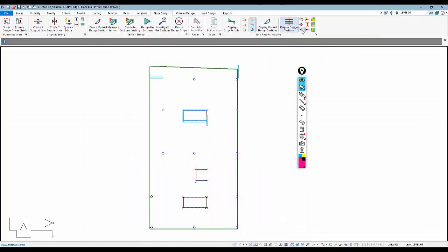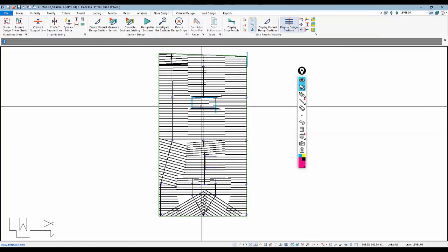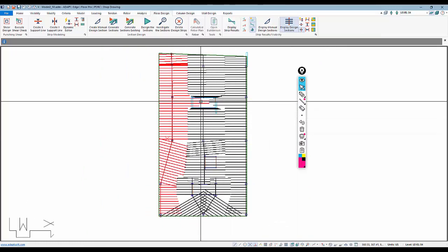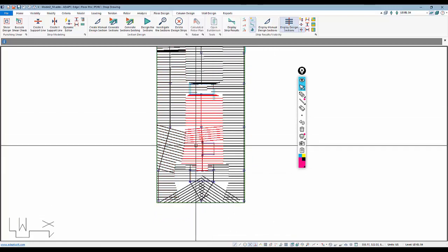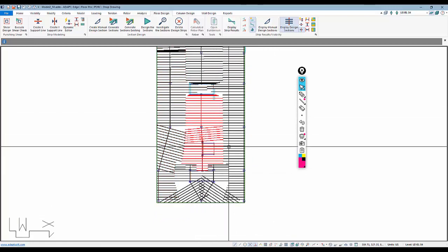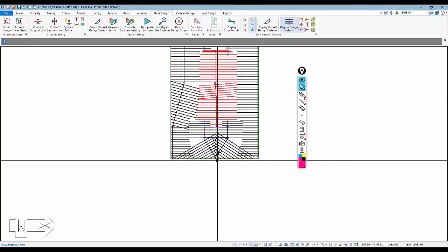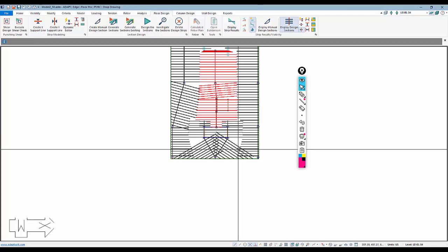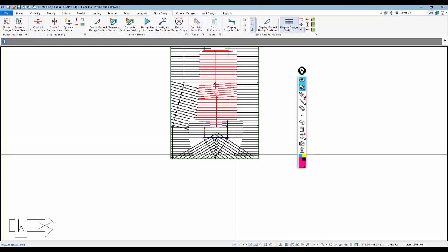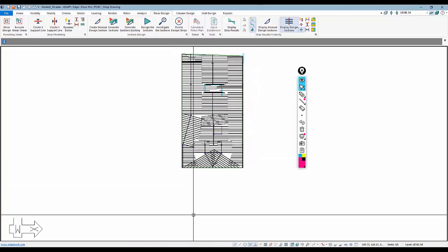We'll switch over now to the Y direction, and we see we have kind of the same thing going on. This extends through the opening. The same thing here. This actually extends into the opening and out of the opening, which we definitely want to avoid. And here you can see there's a little bit of overlap right there with these sections, and also over here. So I can use splitters to handle all of these things.